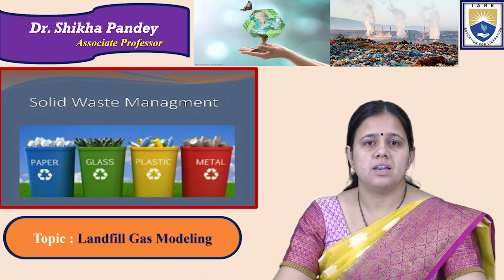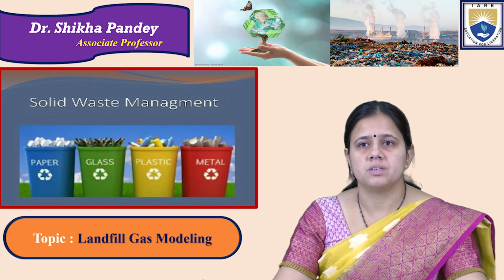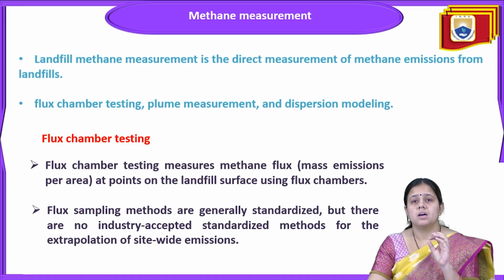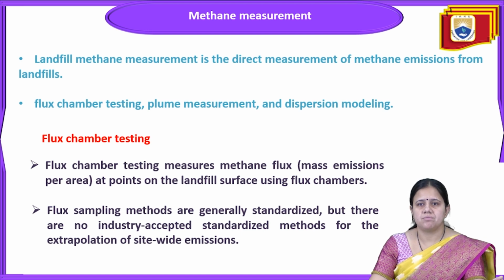In this lecture series of the subject Solid Waste Management, today I will discuss landfill gas modeling. Previously I discussed the collection of methane from the landfill. At the initial phase, aerobic conditions will be there. When oxygen deficiency occurs in the landfill, anaerobic conditions start inside the landfill. With this anaerobic condition, the methanogenesis process will start, and methane production begins in